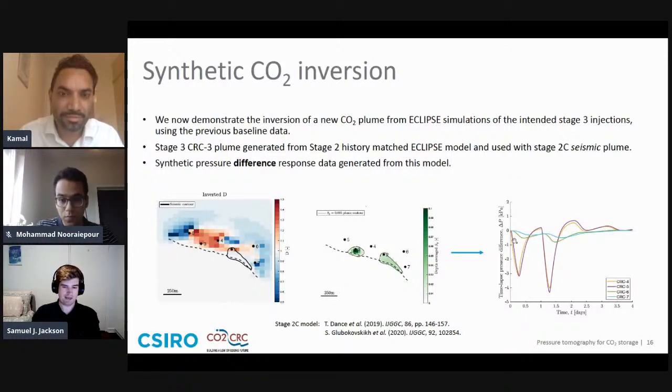And the generation of that pressure response is different, and you can actually pull out different information from the field. So the combinations of different injection modalities can really inform different frequencies and different spatial length scales in the domain. You might do a very short injection or a very long injection when you're trying to uncover information about the different length scales of heterogeneity, at least for aquifer characterization.